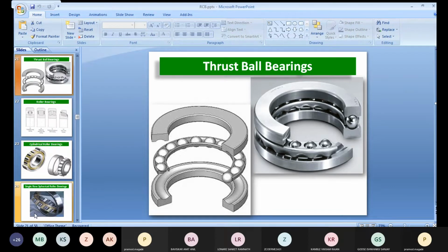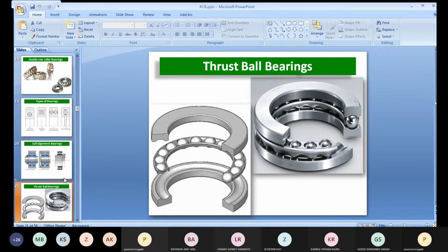Okay. So this is called a thrust bearing. After thrust, we will see the angular bearing, which I did not show. In an angular bearing, the balls are placed so that the angles are situated actually. Some 10 degree angle is there with respect to the horizontal plane, and that will be maintained and it will help to take a maximum thrust load.